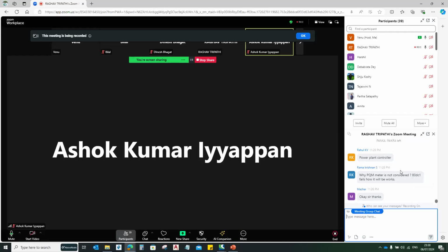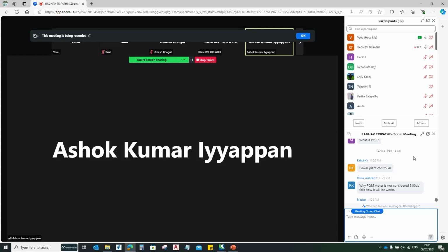Power plant controller is nothing but the CPU, where you have the trip relay reset scheme as well as the circuit breaker close command and auto reclose command. Sync check functionalities will all be located in this power plant controller, which we can call a CPU only. And do we have any relation with the protection relays? Any input or output received from the PPC for the relays? Yes.